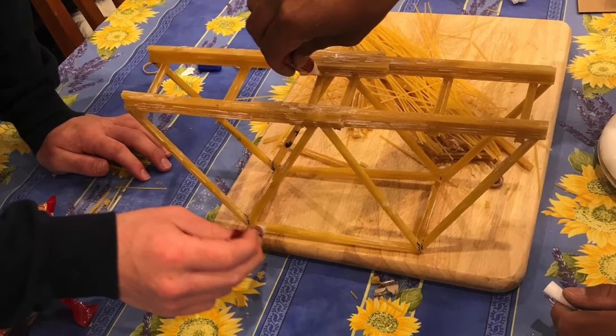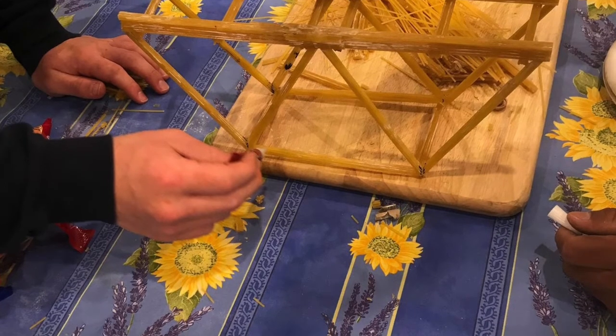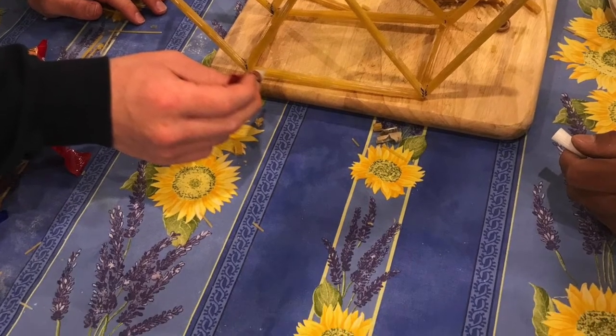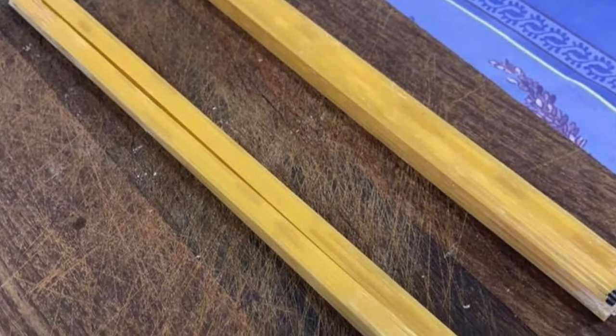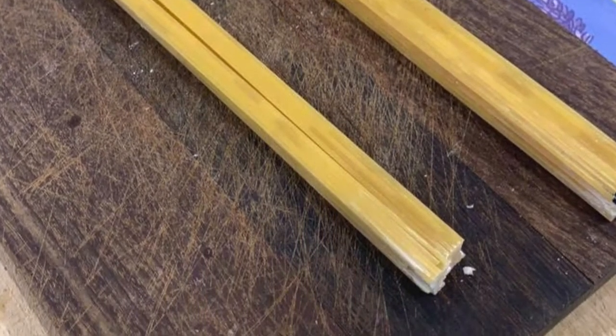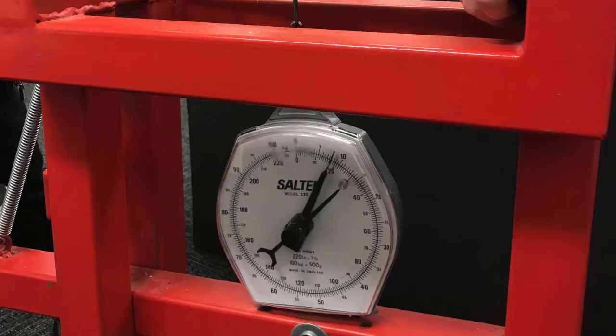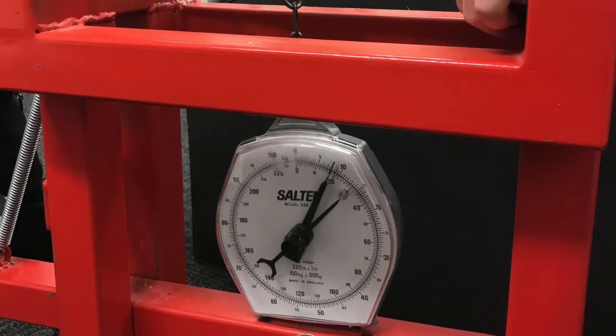Through the use of equilateral triangles to disperse the loads on the bridge, we thought that this would reduce the forces to only compression and tension. With the 2 big beams at the bottom of the bridge, we believed that the forces would focus on the middle of the bridge, which became evident through both testings.